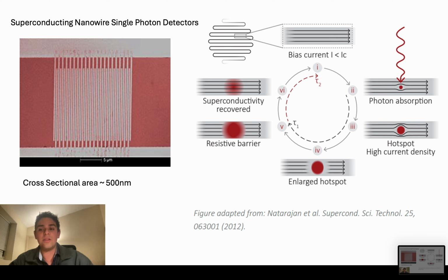And there's also this challenge of fabrication where if we have devices that can be fabricated to be a little bit larger, we can use optical lithography instead of electron lithography, which will make it a lot more accessible and a lot cheaper. So there's a lot of research being done to find these trade-offs as far as fabrication and making detectors that can work with the research that you need, right?